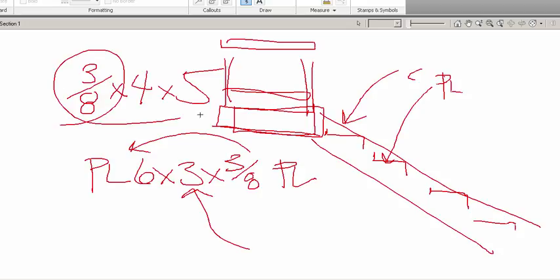Technically, this format is a little bit more standard, more approved, but the designers, they're just trying to communicate their ideas, so they don't sometimes stay to the standard that well. So just be aware that the dimensions could be before or after the rest of the size dimensions or the actual size of the plate. Thickness is a priority, and the PL can be located in 2 different locations. Not necessarily saying it's correct, I'm just saying that's how a lot of people will do it.